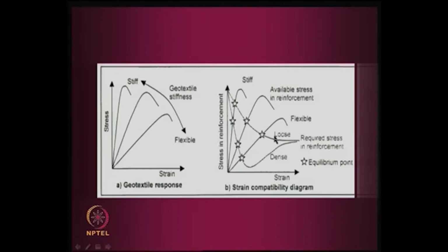So, how do they match? This is very important because, as I just mentioned, the performance of the reinforced soil is a function of the force mobilized in the reinforcement, is it not? Say for example, you apply some load and you have a reinforcement, the moment there is a force developed in the reinforcement, it takes care of that load. The tensile force comes into the picture, it starts acting. So, how fast it can act before it takes more deformation is very important.